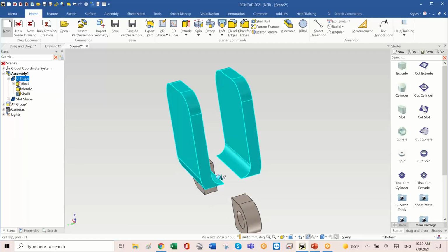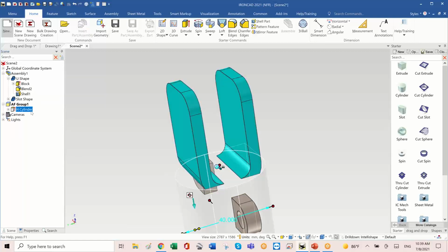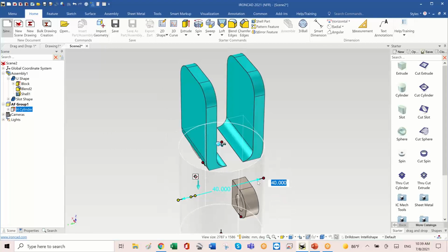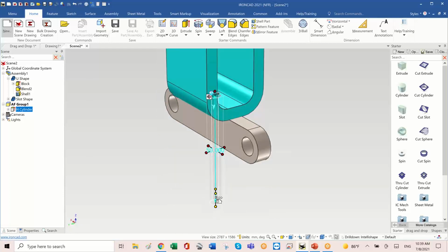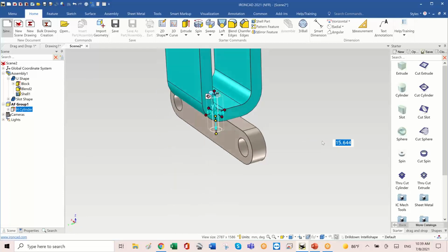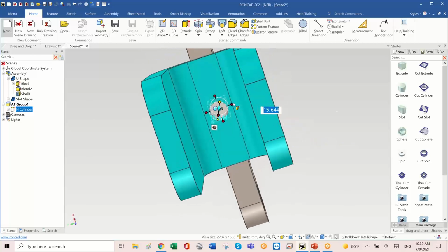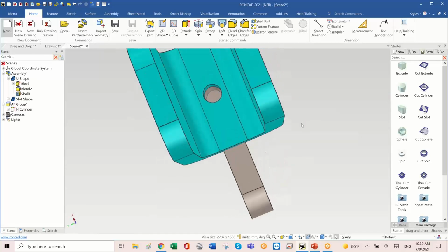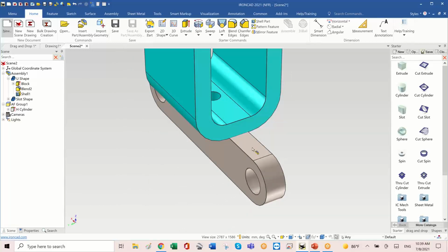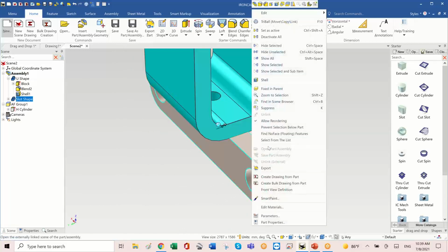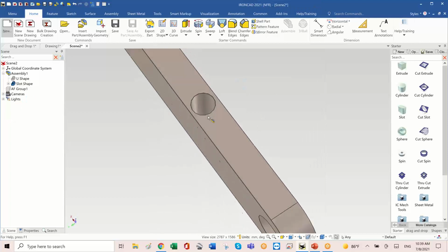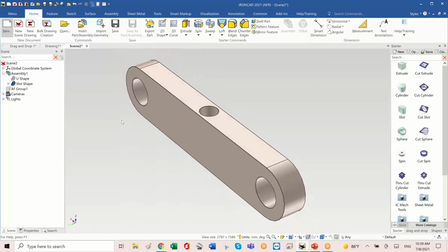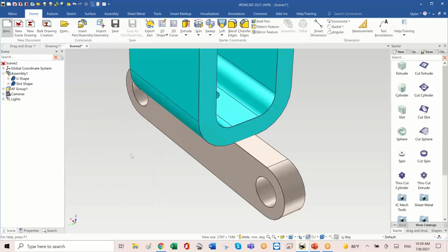And that's a little big. That's a very big shape. So hang on, let me grab that. That cylinder was way too big. Not 40 mil, make it 5. What did that do? That came through and it dropped this cylinder all the way through. And if I wanted to, it has now created this through this part. And if you'll notice, if I select on this and hide the unselected, it cut into this as well. So I was able to use this for everything. Show all.